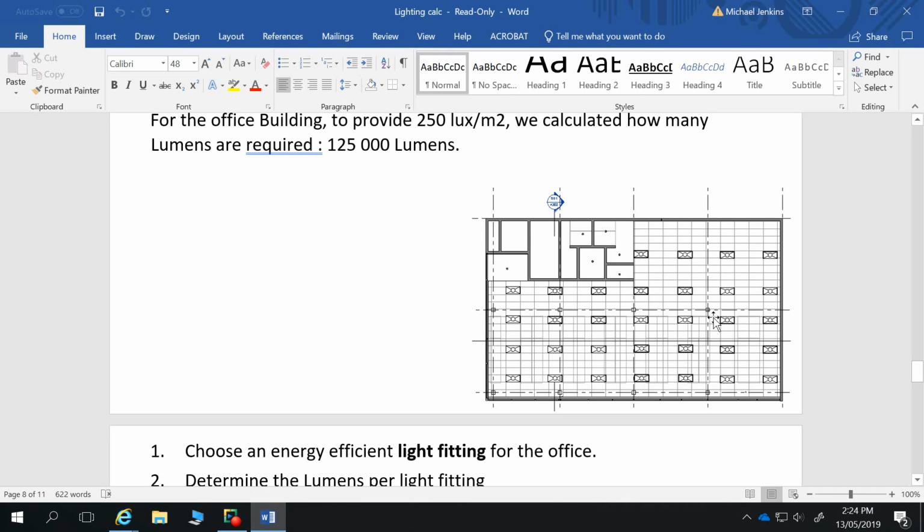I'm expecting that that's the type of reflected ceiling plan you do for this project as well. It makes it easy to have a grid type ceiling system, because that's something that's easily modified for changing use. You can have your electrical supply with just your 3-pin sockets to your lighting bays, spread about the place in the ceiling up above that acoustic tile setup.